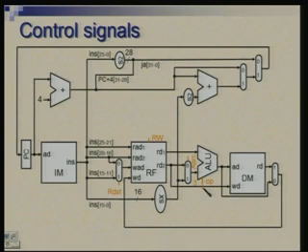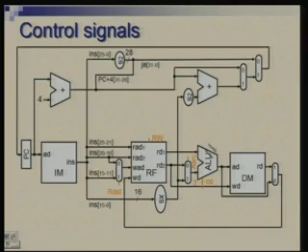Recall the design of the ALU which we had done. We had some circuit, and then at the end there was a 4-input multiplexer, which will select the AND output, or the plus minus output, or the output for SLT. So 2 bits are required to control that, and another bit to choose between add and subtract. So there were a total of 3 bits. I am labeling that as OP, standing for operation.